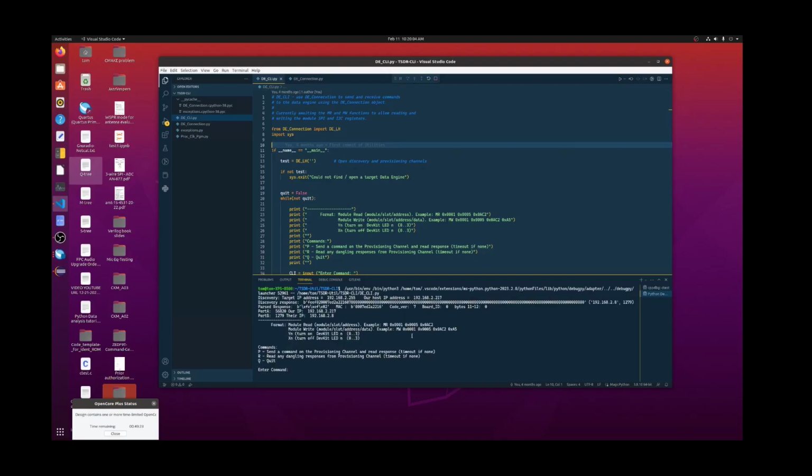And here what it does is it first uses OpenHPSDR Discovery to go out and look for an OpenHPSDR module that answers the discovery. In this case, it's found the module on 192.168.2.8, and successfully identified the particular unit. We now have available to us a few commands that implement this module. The first thing we'll do is send the P command, which opens and allows us to send a provisioning command.